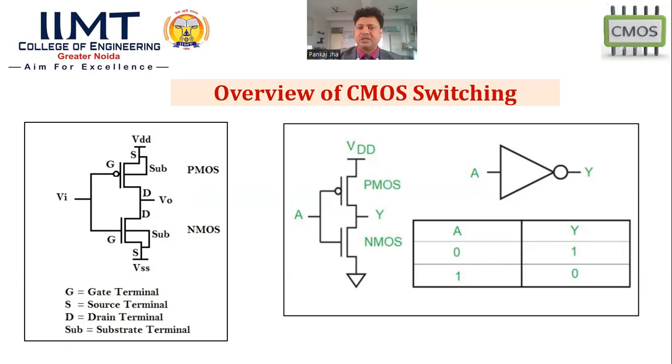known as pull-down. So in the second figure, you can see I have made an inverter where A is the input of PMOS as well as NMOS, because we are giving the same input to both transistors simultaneously. So when we apply zero voltage as input, PMOS gets saturated, that is VDD will come across Y where we are taking our output, and if A is high then NMOS will be in cutoff mode. That is, when we give zero input, the output will be 1.